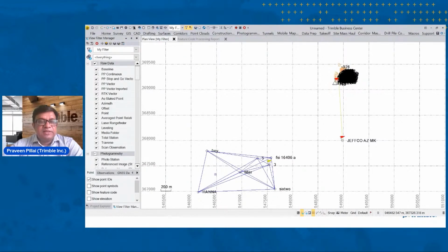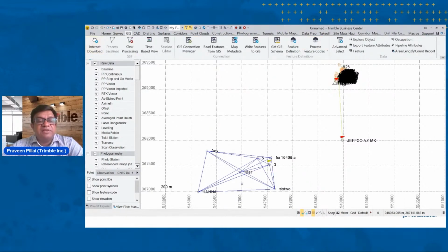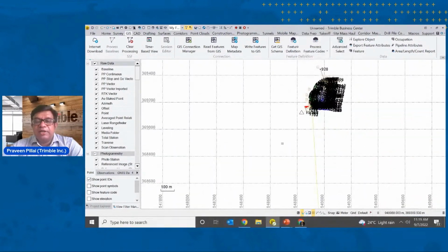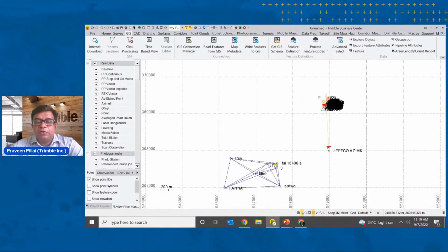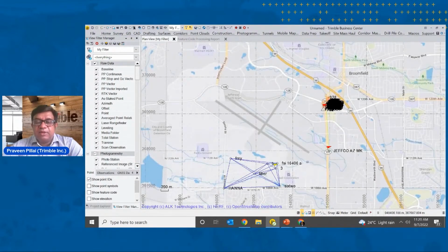So everybody is able to see this, right? So this is the Trimble Business Center software. Okay, a very easy to use software. You can see here various menus are available. Okay, what I have done is I've just imported a few GNSS data. These are some level data, some total station data, and some RTK data. So all the data can be imported here. And then if you want to toggle between some background images, definitely you can have a background image as well. Okay, so any background image is available, OpenGIS map, or we have got various other raster background maps as well. We can load that.